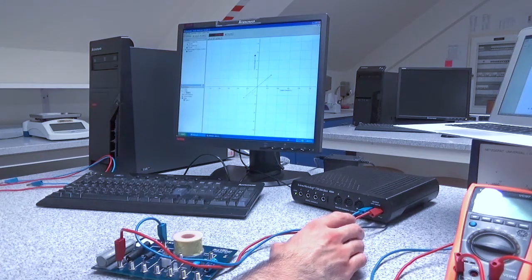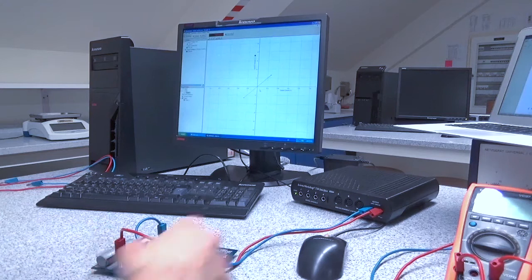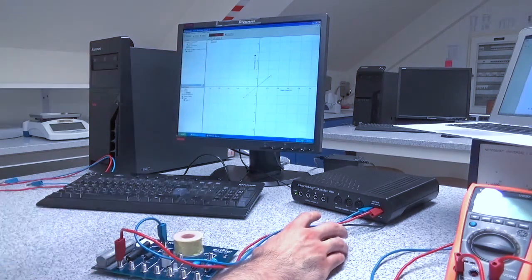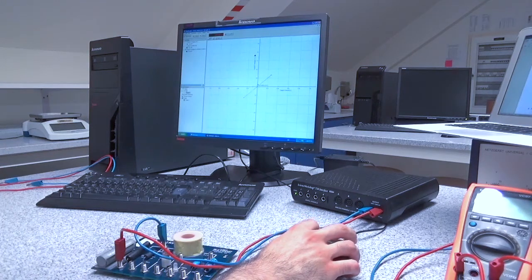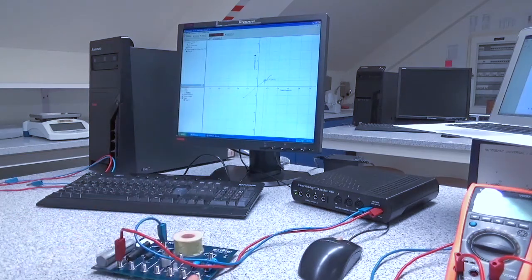And as we can see, the relationship between the voltage and the current is a straight line relationship, which is validating the fact that a resistor is an ohmic device. Now what we need to do next, over here we are going to click on that cursor, which is the XY coordinates cursor, and then we are going to be sliding these XY coordinates across the straight line in order to pick 4 different points for the voltage and the corresponding current.